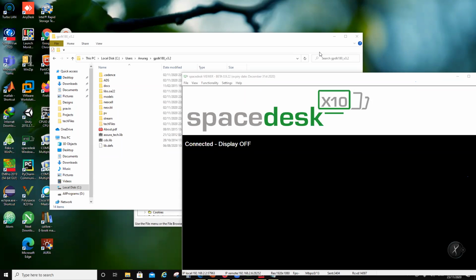You would be doing a two-step solution: doing EM simulation on passives, bringing those passives into the circuit simulator, and then simulating it. This is with everybody other than the multi-physics simulators like Sentaurus TCAD and COMSOL and stuff like that. And then there is CoventorWare. There are lots of other tools which will allow you to do both, but then the simulation is going to be very time-consuming and resource-consuming. So all things are available to you these days.